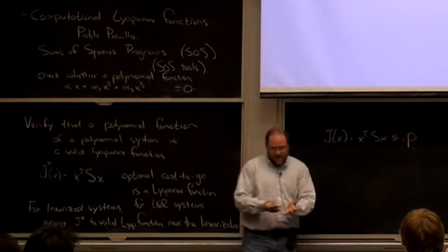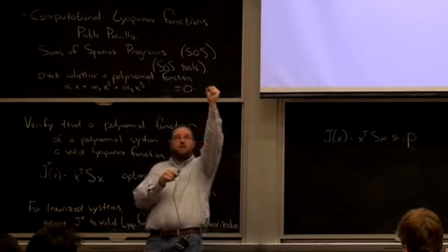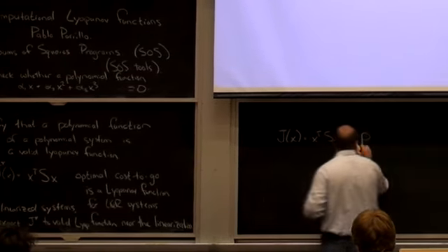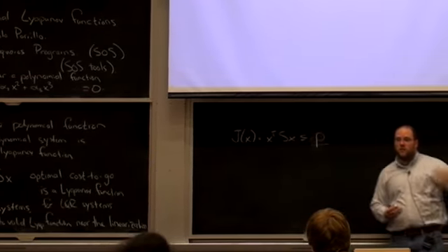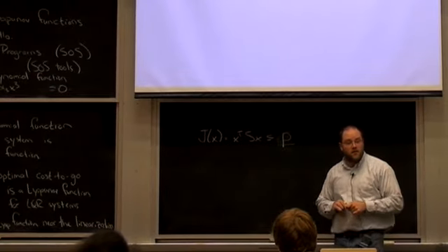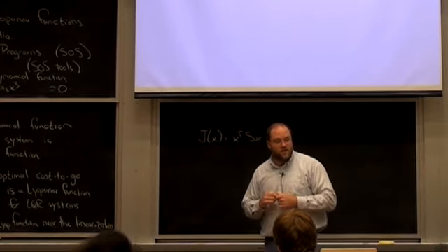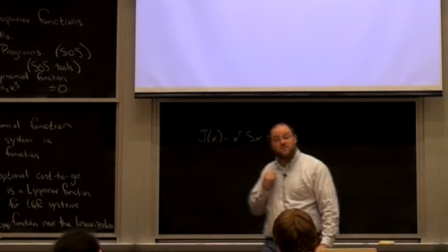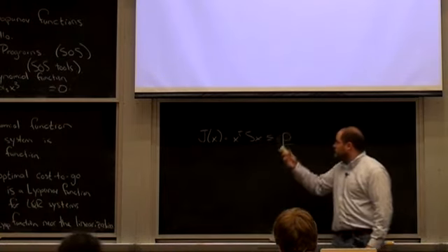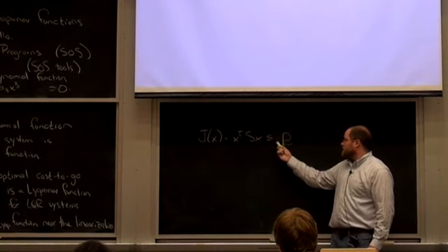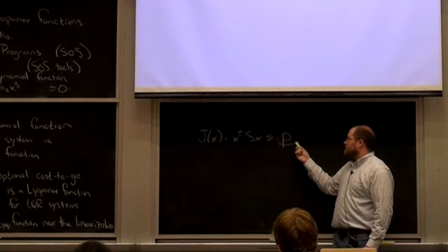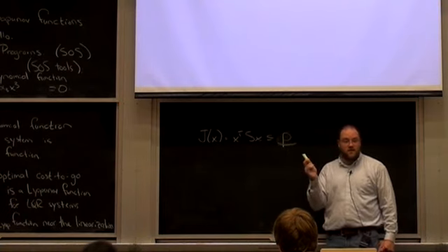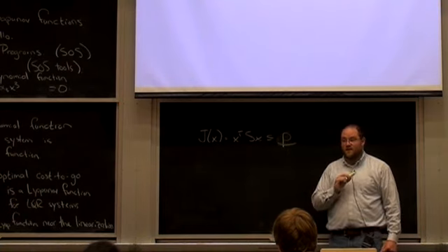At some point, as I move farther from my fixed point, the cost is going to get higher and higher, and at some point it crosses some scalar value rho. So I want to call my basin of attraction for this system the place where my cost to go reaches rho. And we've got a program, thanks to Sasha and Pablo, which will try to estimate this scalar value rho as a scalar representative of the basin of attraction of my system.